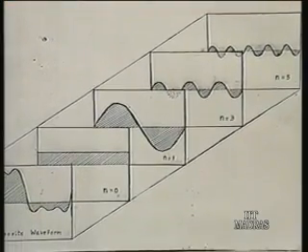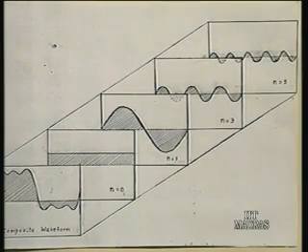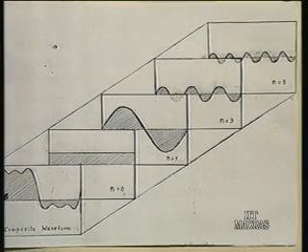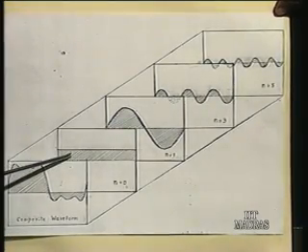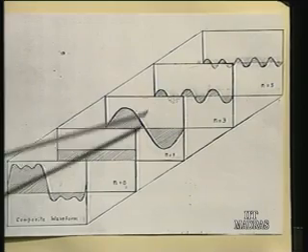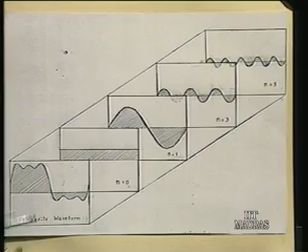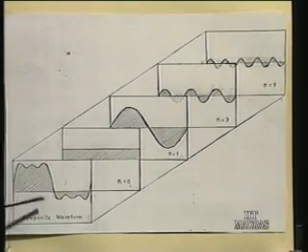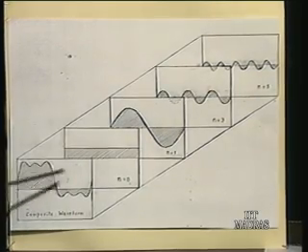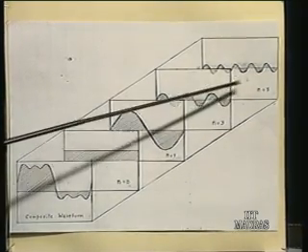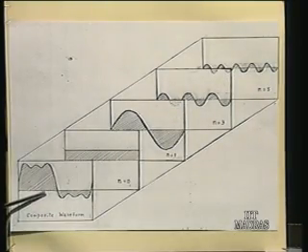which shows how different harmonic components add up to build a composite wave. Suppose this is a composite waveform that we would like to have. In this case, there is a DC term, there is a fundamental, there is a third harmonic, and there is a fifth harmonic. The composite wave that I have drawn here is one which is built from this. Therefore, it really means that there are only 4 terms in its Fourier series expansion, and the 4 terms are the DC term, the fundamental, the third harmonic, and the fifth harmonic. If you add up all these curves, 1, 2, 3, 4, it will add up to this.